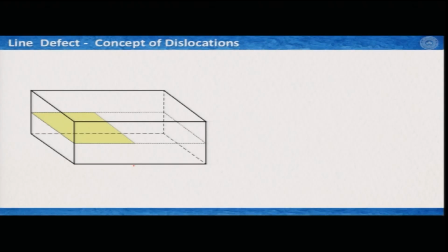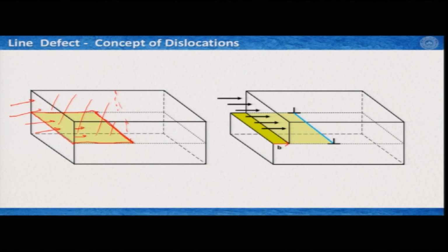Now, what we have in this illustration is a block, say a crystalline solid, and then by some means we made a halfway cut through the middle of this block. Because this would be deforming plastically, to visualize better, let us assume this is a piece of rubber. If you push the top part only on this side, leaving the base, it would try to squeeze in this direction, but because this part is fixed, at this segment the material would be much denser.